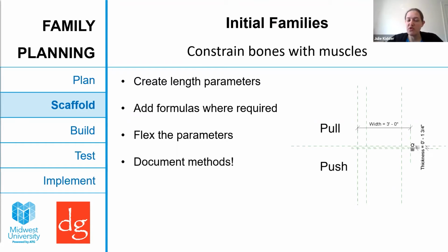So with the door leaf, before I modeled any elements in the family, I made sure that I could change the width and the height and the thickness of that panel, and that those reference planes moved the way I expected them to.